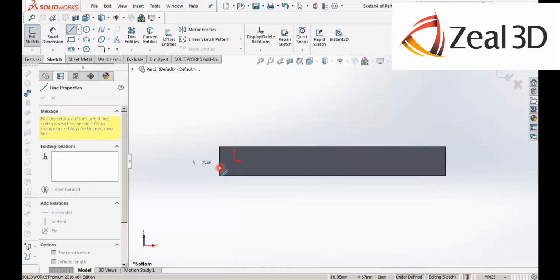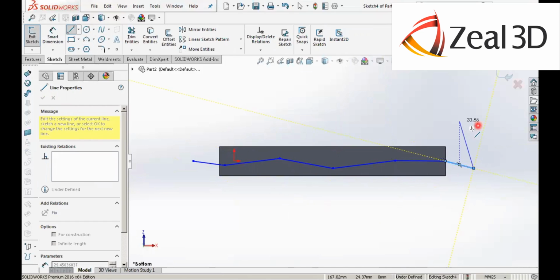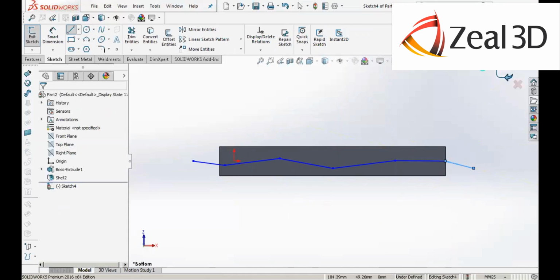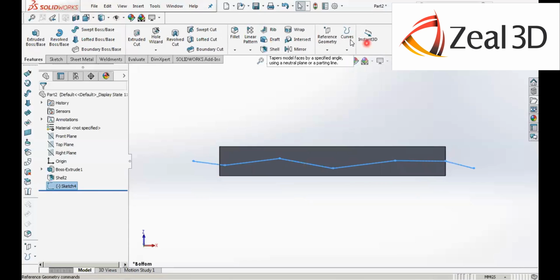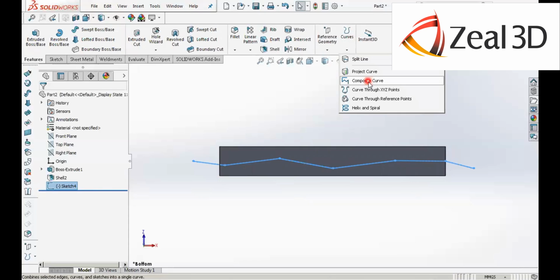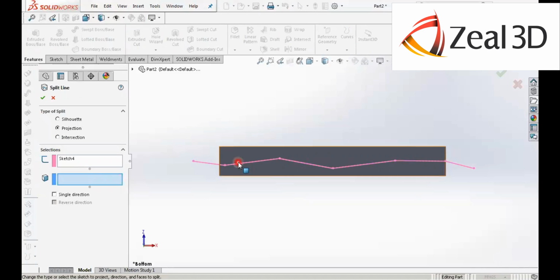Apart from it, the other two types which are available are the parting line and the step parting line. But for that what we require is to create a step part, or basically we need to split the face onto which the draft is to be created. So for that we need to create a certain kind of curve or line with edges, using which we can split the face using a split line feature, and this will split the face into two different parts.